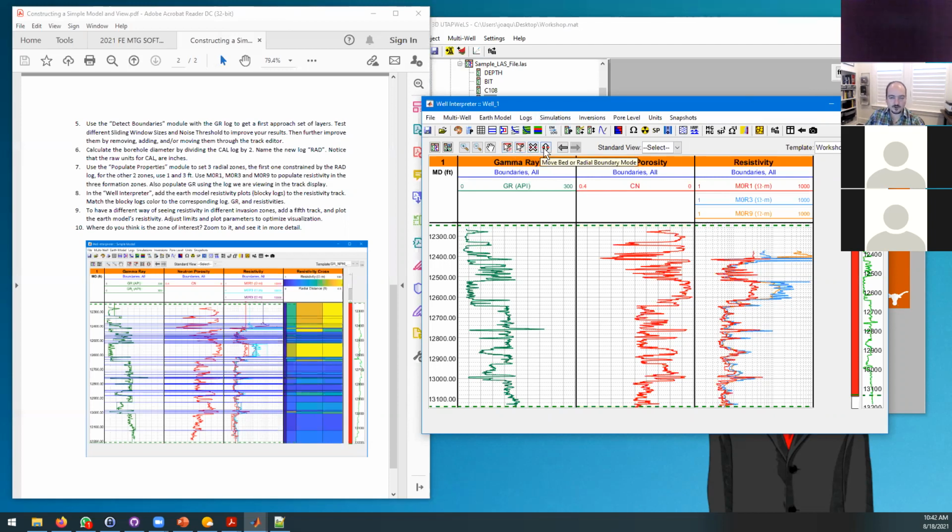You have these 4 controls: the create new petrophysical boundary, create new property boundary, delete boundary, and move boundaries. The difference between a petrophysical boundary and a property boundary is that property boundaries are like fluid boundaries. Petrophysical boundaries set different distinctions between rock petrophysical properties, for example, porosity and so on.